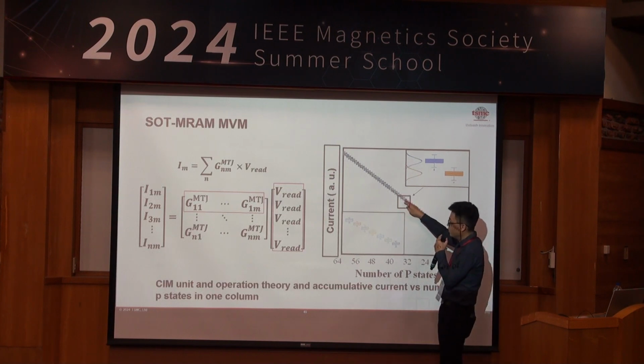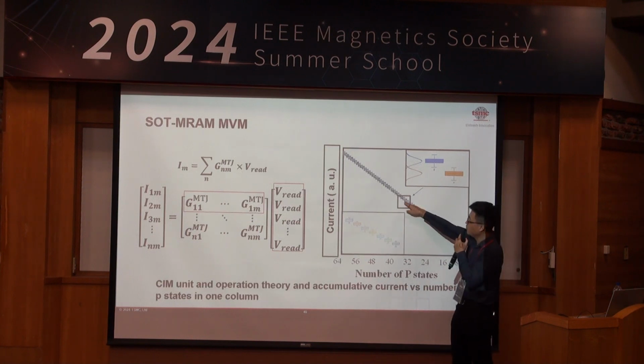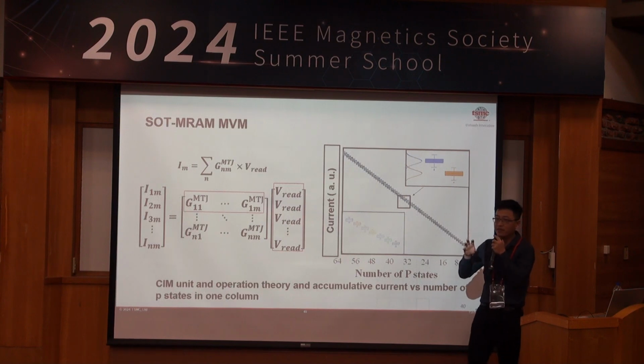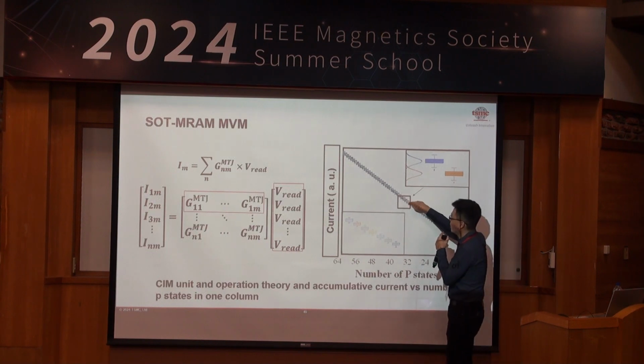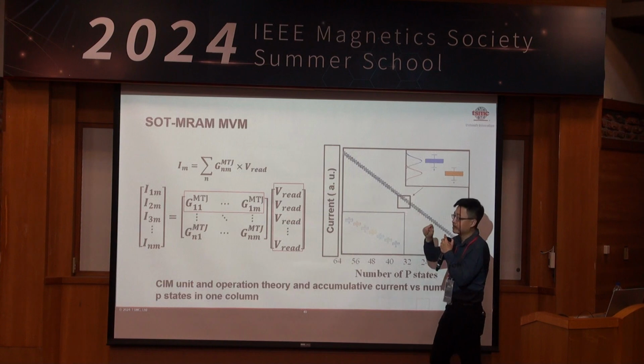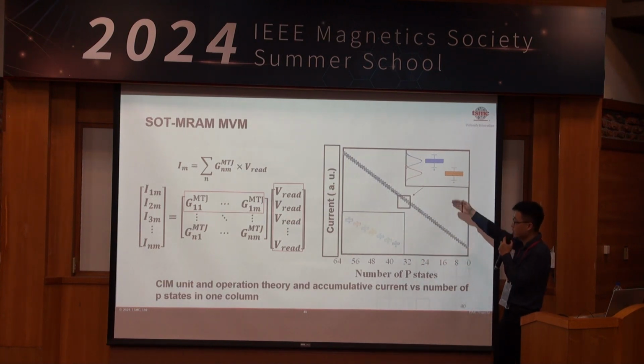Here we guess the most challenging level would be in the center, because you randomly have around 32 ones and 32 zeros that give you a high and low current. Even though we check the center point, the overlap is less than 2%. So I think this is a very good demonstration that we can do multiple levels of the cumulative NVM.